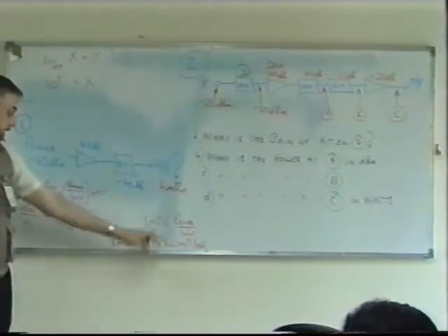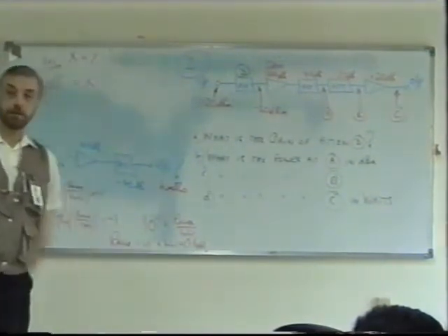Therefore, the power must equal 1 milliwatt times 10 to the minus 1. 10 to the minus 1 is a tenth, of course, isn't it? 1 divided by 10 is 0.1. So the answer to the whole question is 0.1 milliwatts, or you could say 100 microwatts. Put it any way you wish, but that's the answer.